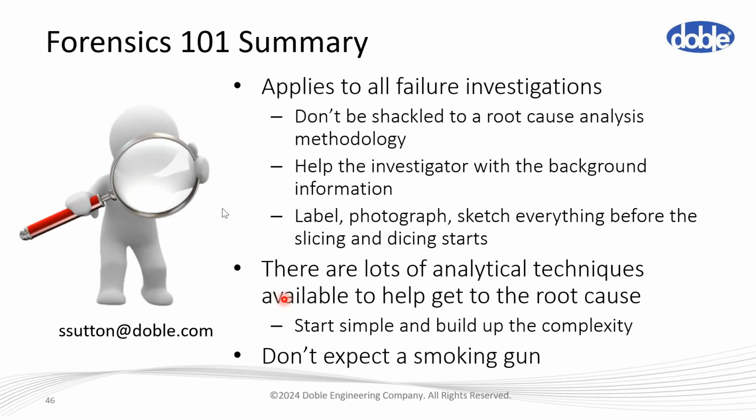I've got another case recently where, again, I think it's a cable design issue. But most of the problems seem to be around installation problems. So generally, if you have an installation problem, it will fail fairly soon after installation. Once it gets past a few weeks and it hasn't failed, there's a good chance it'll still be working 25, 30 years later, unless the cable gets damaged.